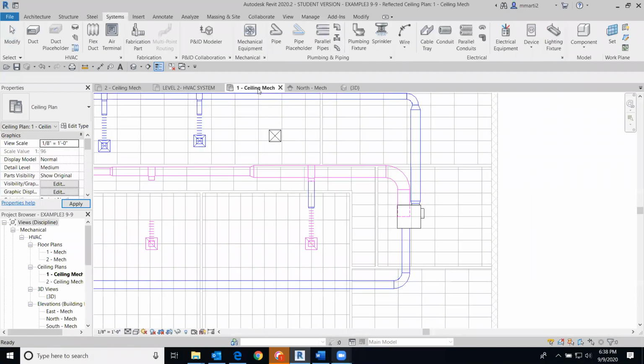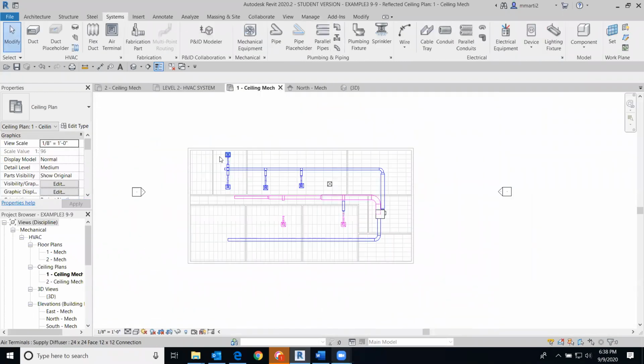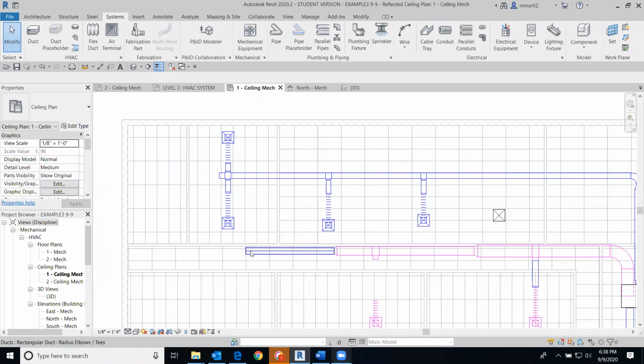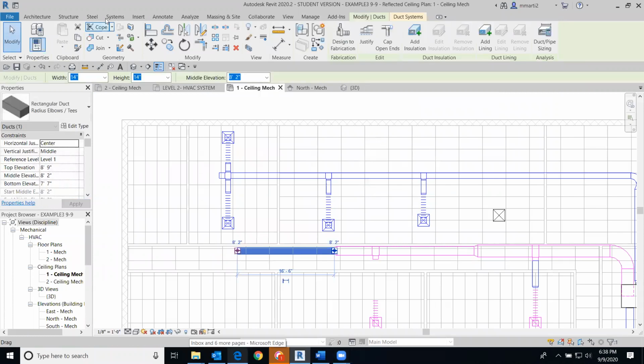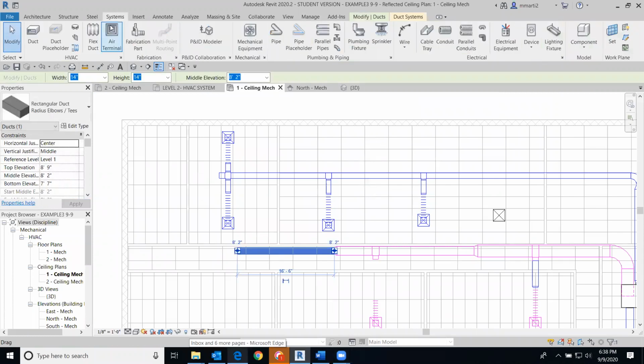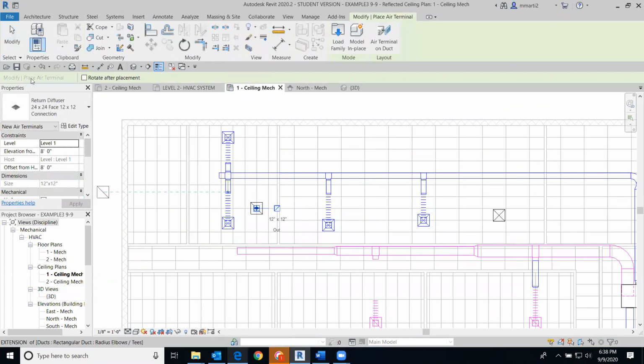Yeah, for your room 101, you could just run 2 vents in here, like I have here, and then for the return air, you can just run 1 off of here as well. So it would just be 1 return air for every room. Some people have more than 1, but I'm just requiring 1. Some people have 2 per room, depending on the size, but we can just have 1 return air per room. Yeah, thank you.